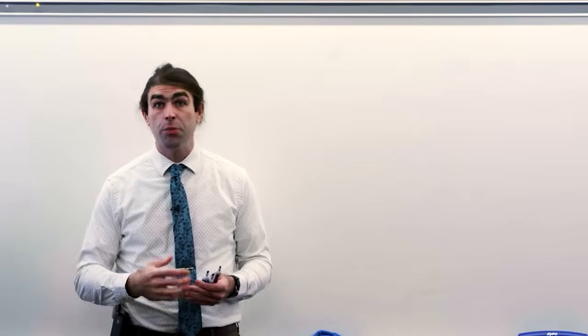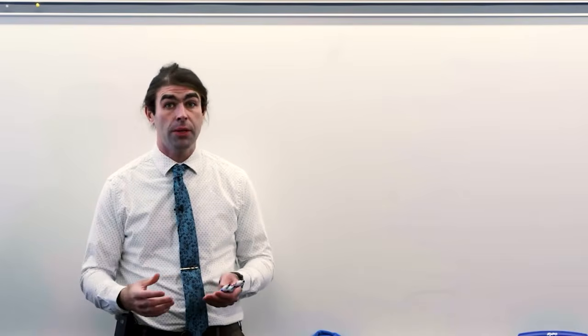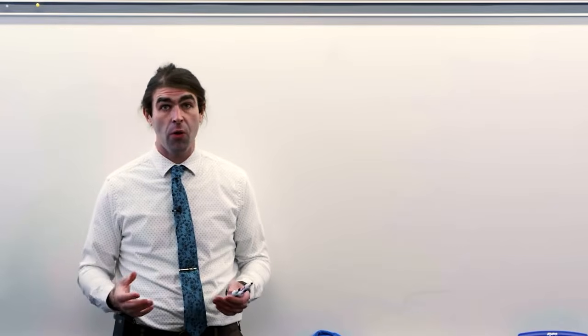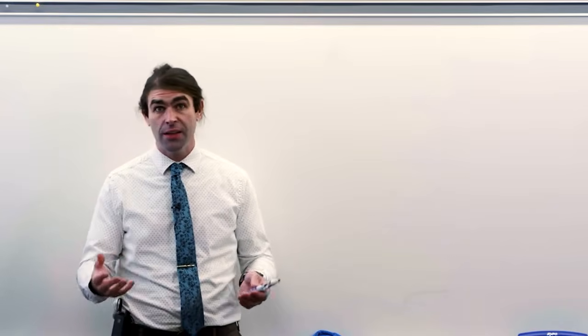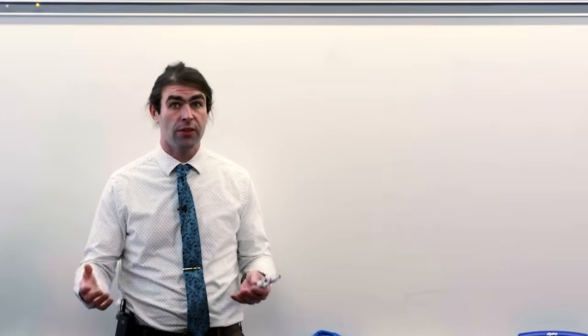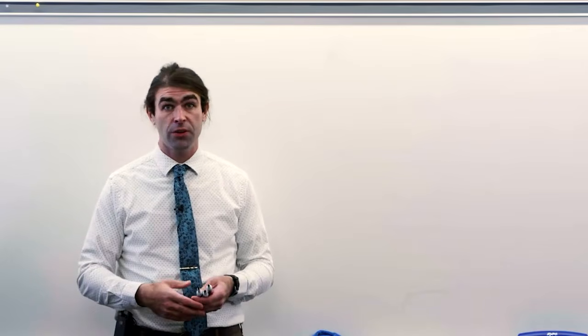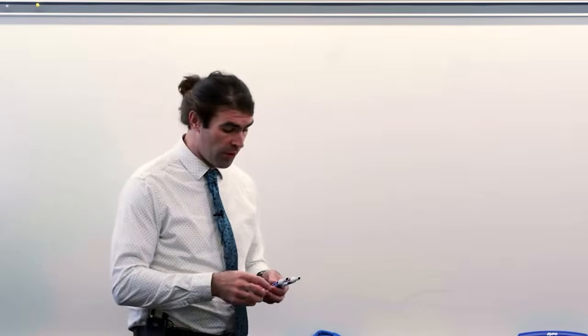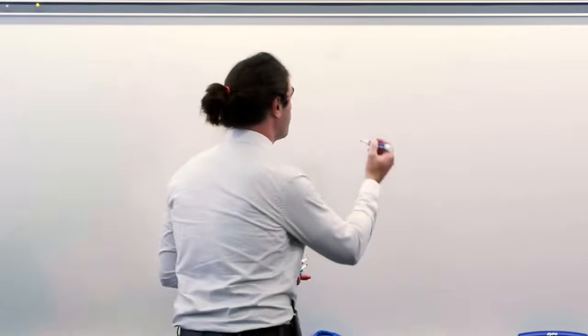So let's dive into patterns. Patterns are very common on drawings where you have one diameter dimension for several holes that are all the same size. In other situations, maybe you have slots or other repeated features, saves room in the face of the drawing. So let me give you a couple examples.